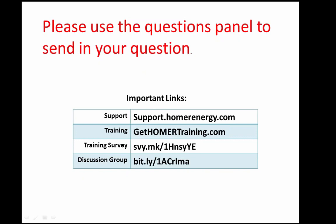Now, there are always counter examples. If you're designing a system without a generator, sometimes it's pretty hard to avoid some unmet load, which is why we have a parameter, the maximum allowable capacity shortage, on the project page to allow a little bit of unmet load, which is hard to avoid in a system without a generator. That's too specific a question to answer without seeing the file, actually.